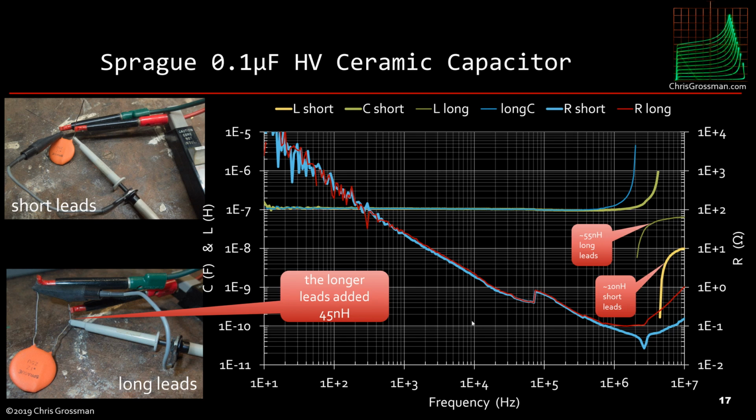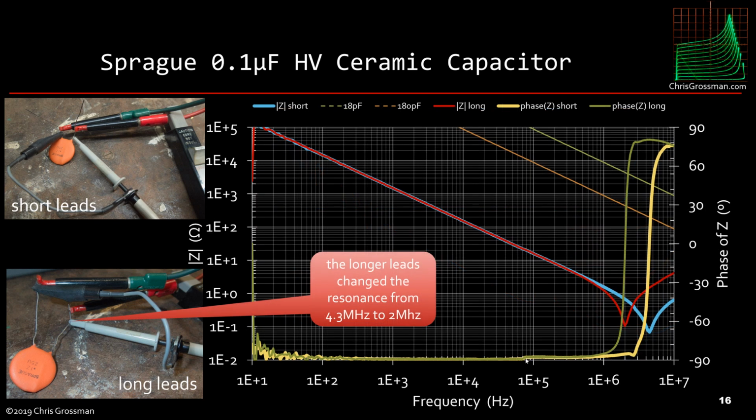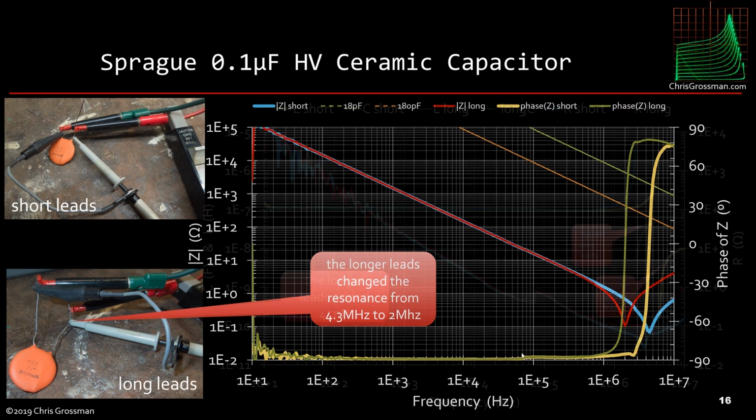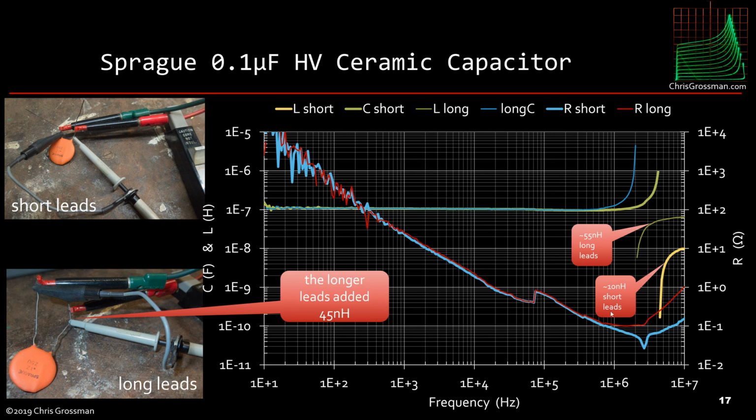If we look back here, you see this little phase glitch. That's again one of those attenuator issues within the scope. This isn't real. There's a little glitch here between 2 and 3 megahertz. I think this is due to something in the current probe, because you'll see this glitch in this range in a lot of the measurements.